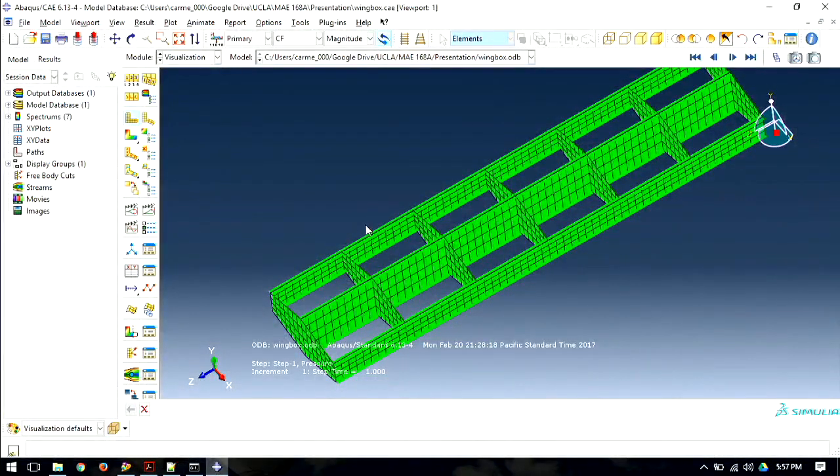So typically what we do, since I work composites, what generally in practice we use for a composite skin, we like to have the skin take the bending loads, because I can tailor my plies so I can give it the stiffness that I want in bending, and I can't really tailor my plies for a substructure which is usually metallic. You do see some composite substructure, but you're not able to tailor it like you can the skin.